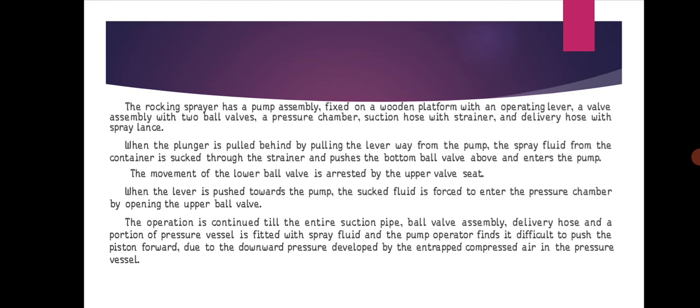When the plunger is pulled up, pulling the lever away from the pump, the spray fluid from the container is sucked through the strainer and pushes the bottom valve up and enters the pump. The movement of the lower ball valve is arrested by the upper valve seat.